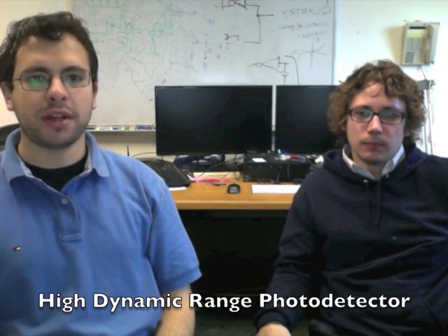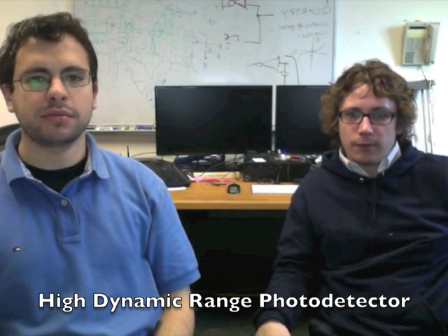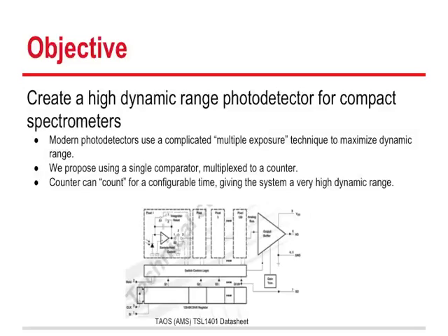In the following video we would like to explain to you the operation of our high dynamic range photodetector IC that we designed and fabricated for Professor Peter Kinget's Spring 2014 VLSI Design Lab at Columbia University. In this project, we designed a photodetector integrated circuit that offers the potential for high dynamic range operation by digitizing light output at the pixel level. The design was carried out using the 180 nanometer IBM 7RF technology development kit. What follows is a brief account of the design process and some simulation and measured results.